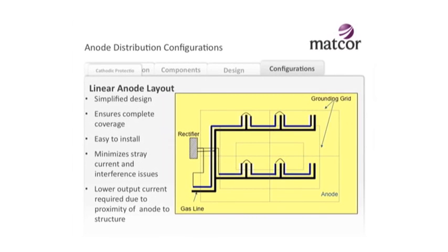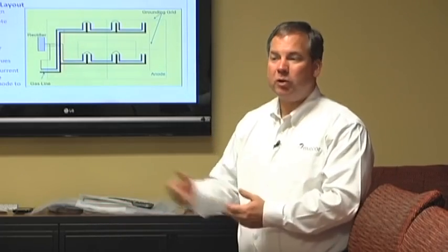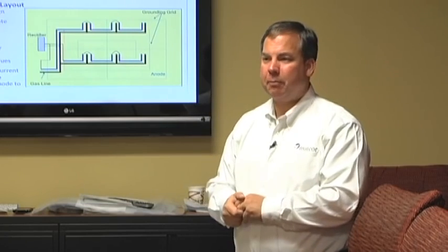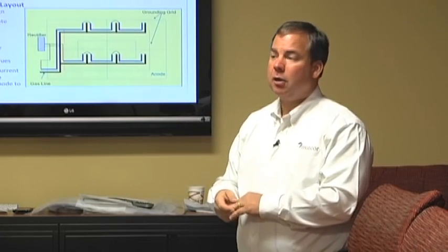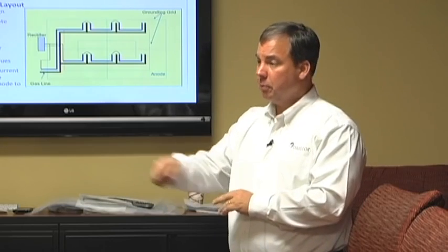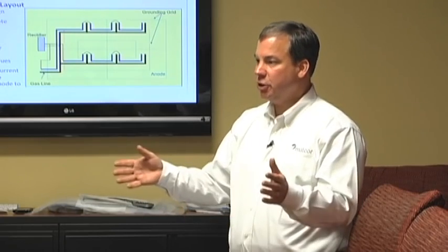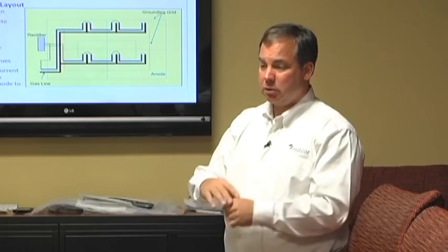If you recall that picture of the pipeline system where I had to decide where to put the anodes, in this case, it's almost foolproof design. I'm putting the anode right parallel to the pipe. Wherever the pipe goes, the anode's right next to it. If the anode's properly sized, it's going to light up that pipe. Okay? We use this a lot for power plant projects and plant piping projects for new construction. New construction compressor stations where they're putting piping in the station. Great design, because as they're putting the pipe in, you just put the anode parallel to it.